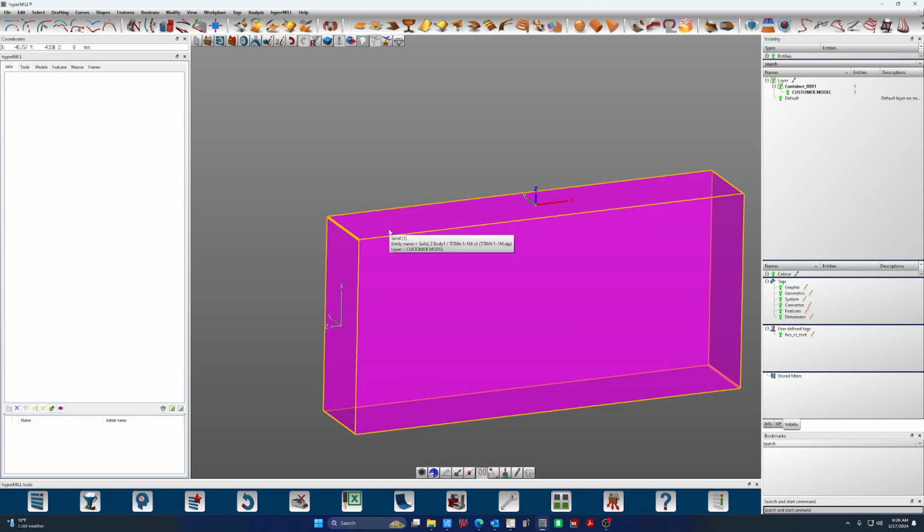Now, obviously, that's a much more brazen statement, and the point I'm trying to make is, if we have lines on our screen that are clearly going in bizarre directions relative to our model, we're going to see ugly machine motion and a poor toolpath. But if we zoom in on the toolpath and we see that same tessellation, that does not mean your toolpath is zigzagging back and forth on your part, for the most part.